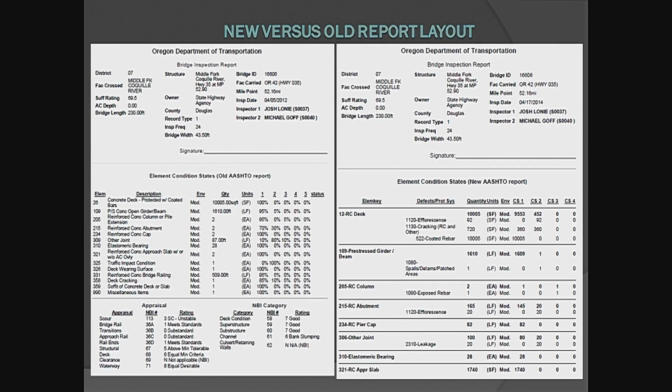If I have cracks just in one little section, but the rest of the girders all look good, then your superstructure NBI condition state is going to read as good because everything looks good on your structure. So really that's a snapshot of your bridge. That's really an important thing for the local agency, people that are getting these reports. If they want to know how is my bridge doing, right there, those 3 values are really going to give you a good snapshot of where you stand.